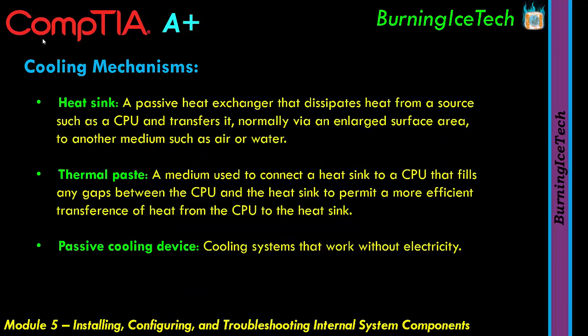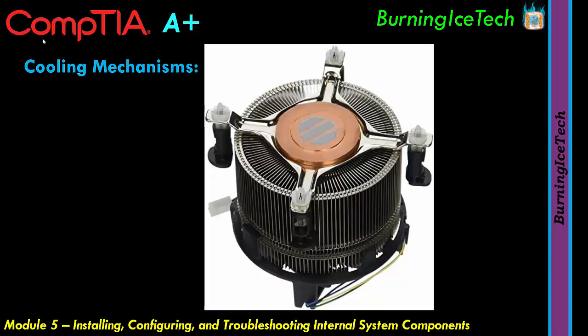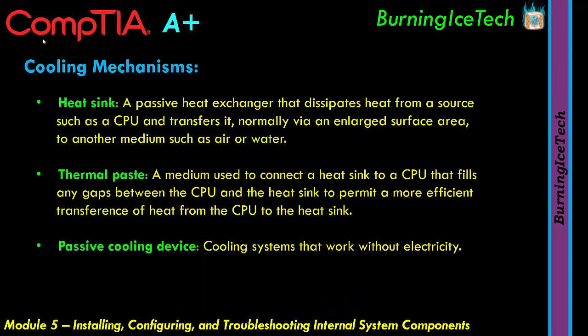If you're going to go and buy yourself a brand new CPU, most of them you'll find actually come with a heatsink included. And that heatsink and that fan, yeah, I actually forgot to mention there's also a fan included normally. That heatsink and fan is designed for that CPU, and they normally actually have thermal paste pre-applied to the bottom of that heatsink, which is pretty cool. So you can just literally go and mount that heatsink on that CPU and you're all set. At the bottom, they obviously mention passive cooling again, and we know what that is. That's a form of cooling that doesn't need electricity.